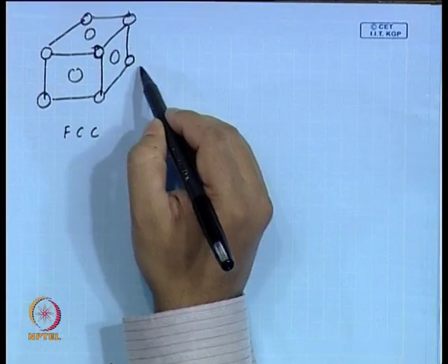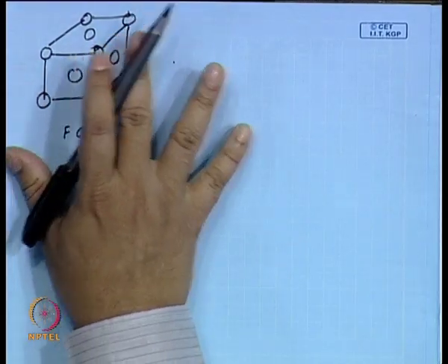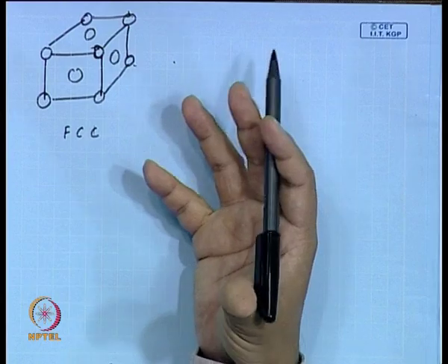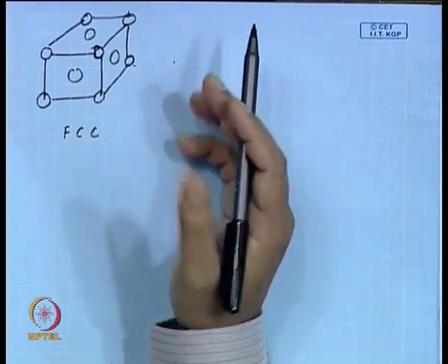Slices are cut from a cylinder followed by atomic polishing phase. So, you get this silicon out from a well controlled crystalline growth process and then cut slices, okay, and then that one slice we are referring to as silicon wafer. So, this is a single monocrystal of silicon. So, you expect that this face centered cubic lattice structure that I said extends to infinity. That means, there would be one, then there would be another one on top, then another one in the right side bottom. So, this is extending everywhere, and the wafer that you get basically has this crystalline arrangement.